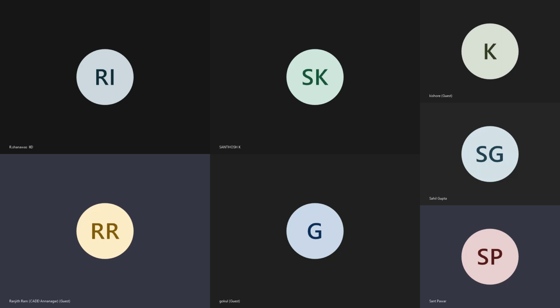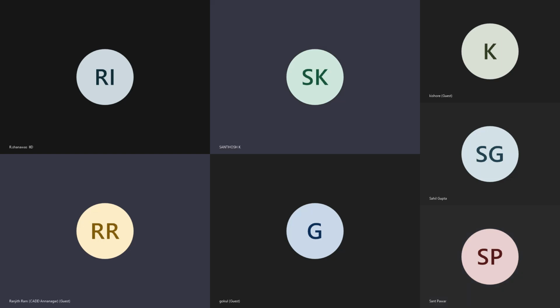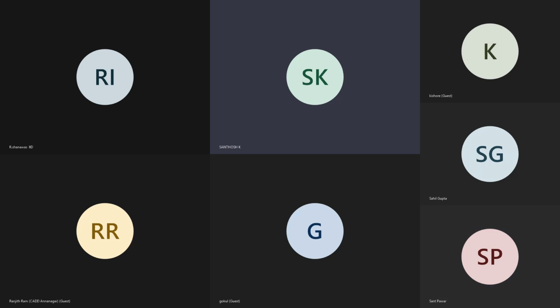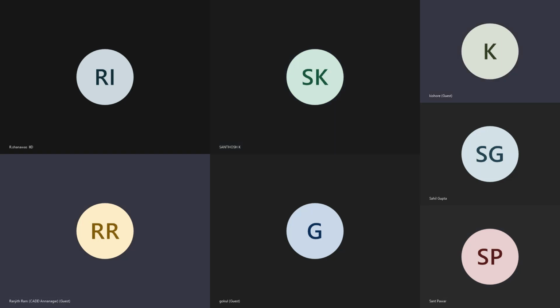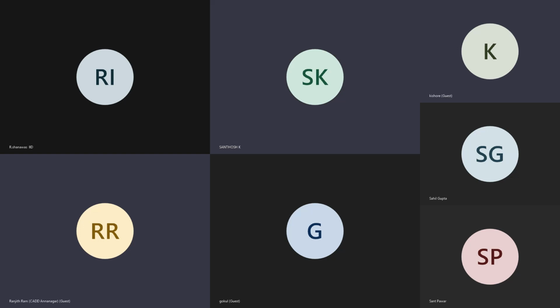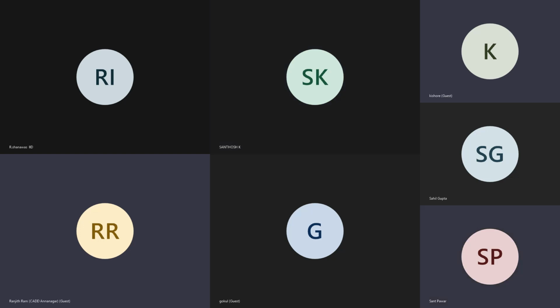Yes, sir. Is it audible? Yes, I can hear you. What did you learn? What did you understand? Yes, sir. So it's a simple problem of flow through a pipe. For everything in Workbench, we have a set of steps, right? First we need to define the engineering data and then geometry, try to mesh it, then give the boundary conditions and look for the results. Likewise in CFD also, the first thing we need to do is creation of geometry, and then defining the wall, and then try to create a better mesh compared to Workbench.